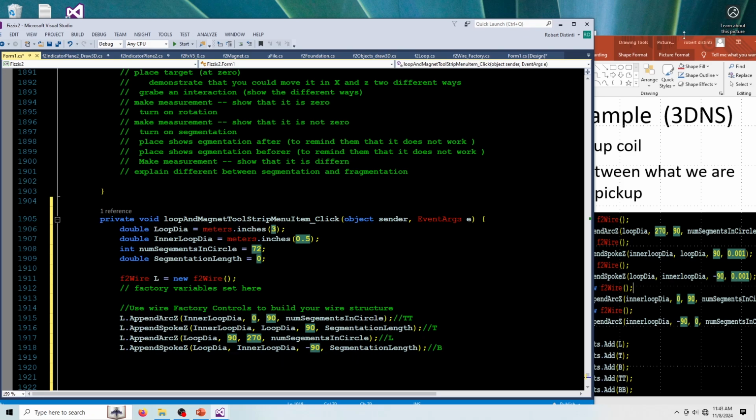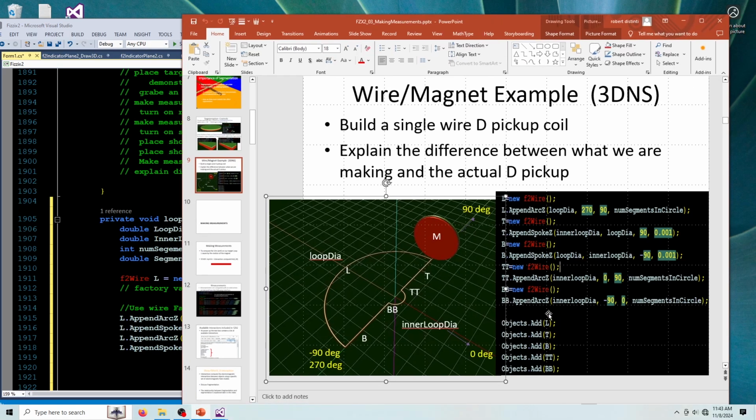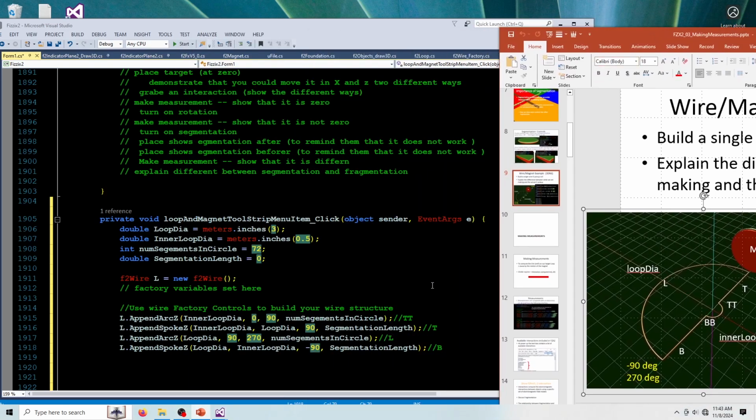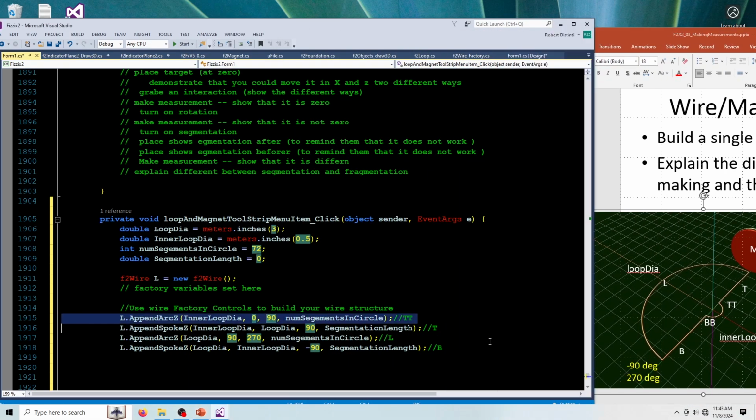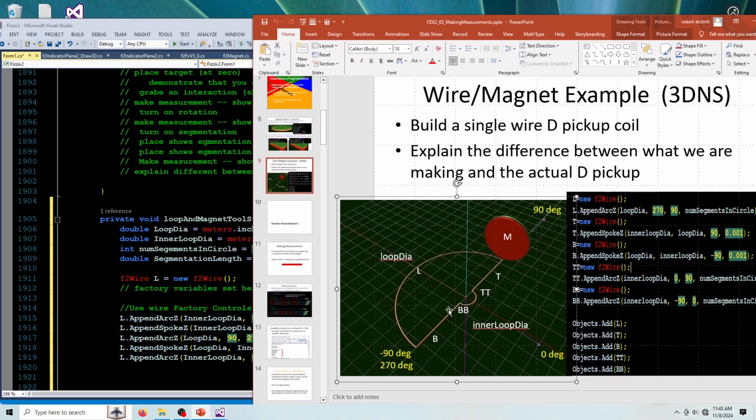And to finish it up, we're going to put in our bottom half of the hub, I'm calling that. And again, we just want one of these little arc guys here. Make a copy of him, makes life easy. Okay, and it's going to be at the inner loop diameter, and we want to draw in this direction. So we're going to go from minus 90 to 0, because we want to draw counterclockwise, which means this number has to be smaller than this number.